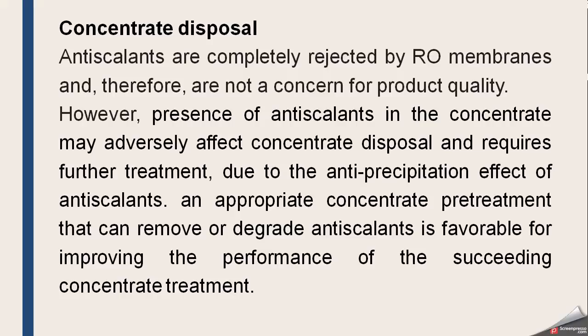will go into the concentrate, and the concentration of antiscalant is higher in the concentrate, and the disposal of this concentrate becomes a problem due to environmental issues. So, due to the anti-precipitation effect of antiscalant, an appropriate concentrate pretreatment is needed. Because these are not easily precipitated and they have anti-precipitation properties, they are normally found in the water. So we require some other treatment so we can remove them by precipitation with these antiscalants,